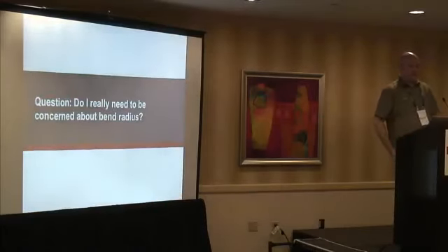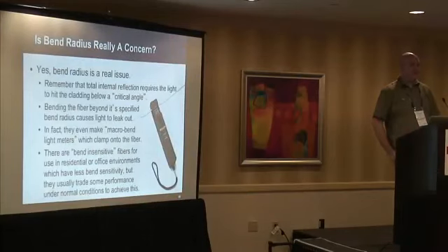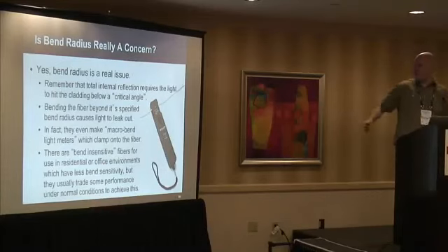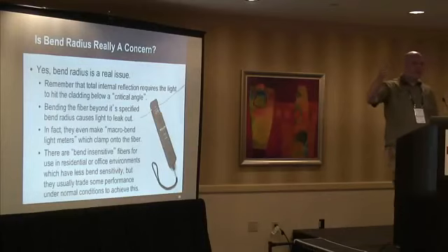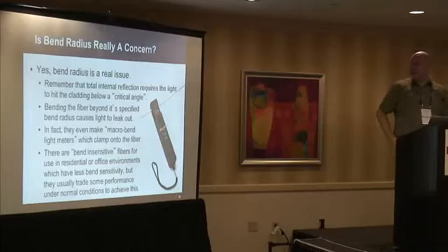Big question that I get asked a lot is, do I actually need to be concerned about bend radius? Yes, you do, because remember that fiber has to enter at a certain critical angle in order to propagate. One cool thing out there is you can actually check the signal on a fiber with a little clamp meter like this. You can actually just clamp it onto the fiber, and it'll bend it a certain way, and it can actually see the light leaking out through the cladding and through this. So you can get a light meter and see what's actually on there.